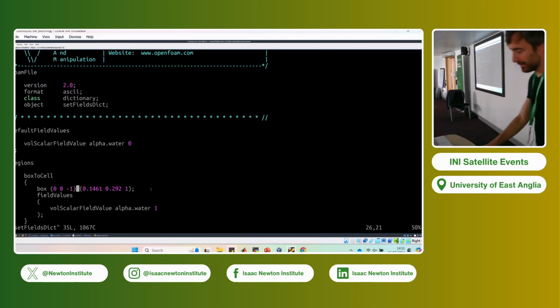And the top Z coordinate of the box is +1. So it's actually +1 and not plus 10 power 9. So the box will go along Z between -1 and 1, the water box. The domain in reality is much thinner, but we don't really care. What we need to make sure is that the box is thicker than the domain so that all the cells within have a value of 1 for alpha.water.